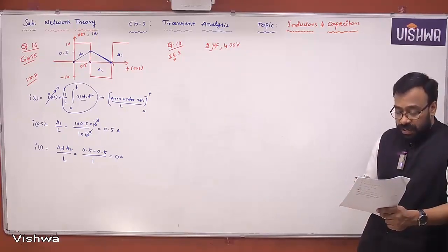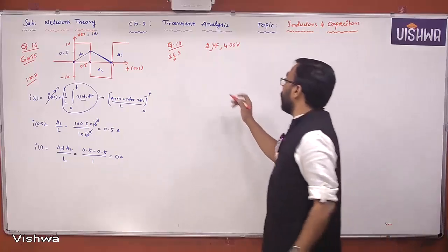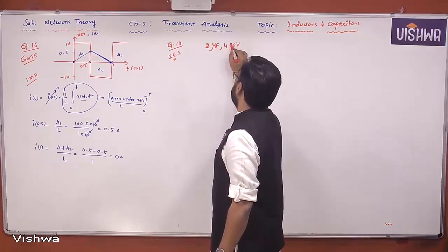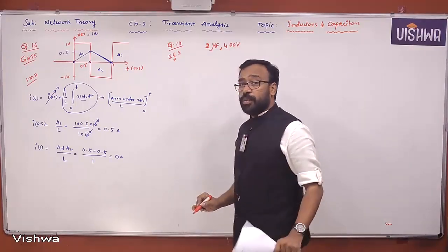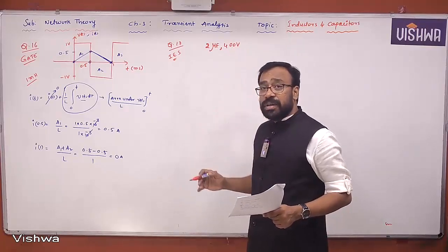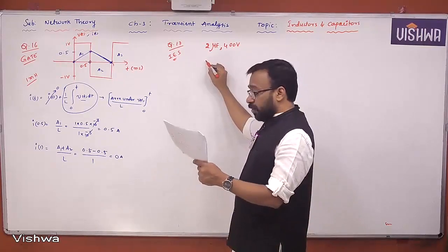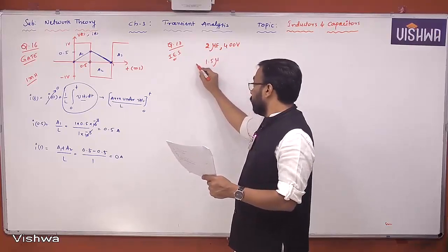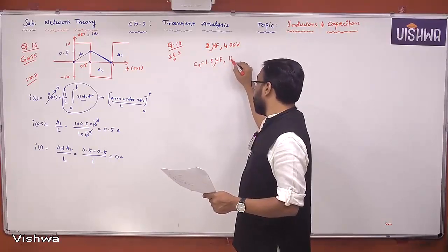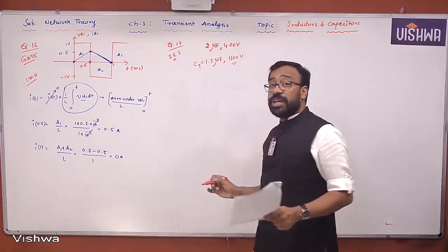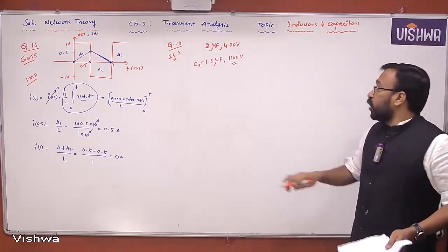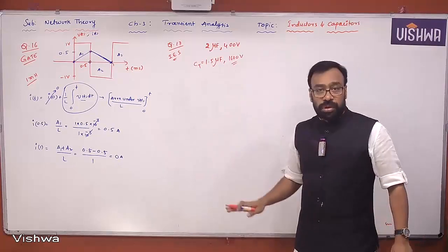Understand? Okay. So here, if you take 2 microfarad, 400 volts, each one is 2 microfarad, 400 volt. Now you want to take these individual capacitors in a number such that the total capacitance value must be 0.5 microfarad, and the total voltage rating 1600 volt. This is the combination we would like to take. Understand all of you? Okay.